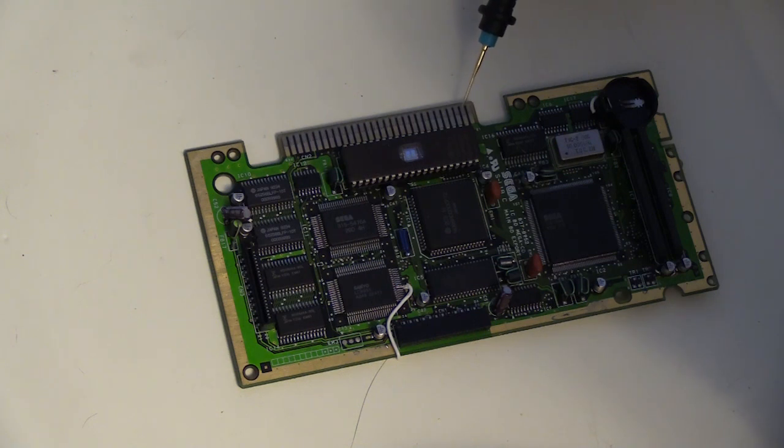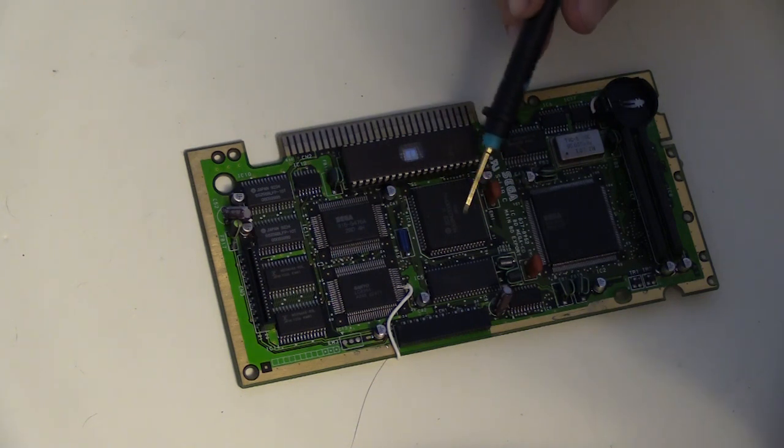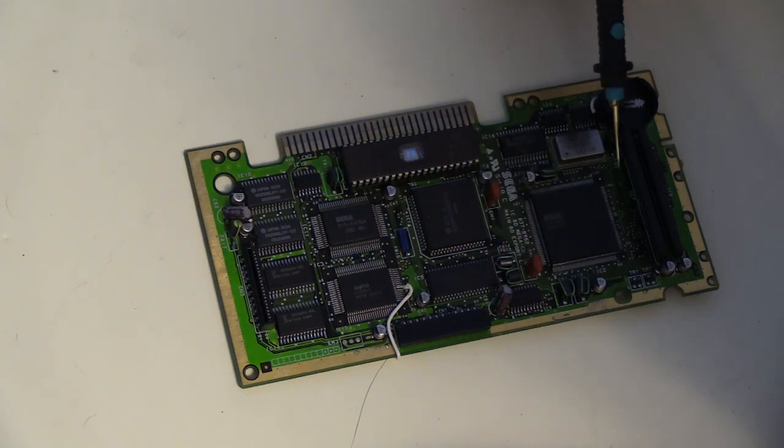Instead, the Genesis CPU communicates through this edge connector, and the Genesis boots off this EPROM just like a game cartridge. And then once the Genesis gets all booted up, the Genesis starts setting things up with the sub CPU and the sub RAM and the engine to initialize and boot the Sega CD part.